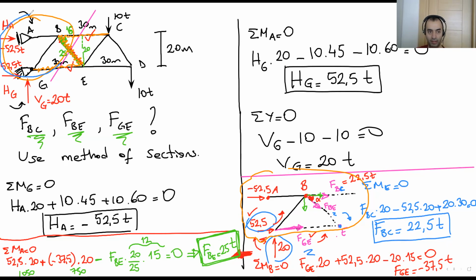I'm using this part. But here, the geometry I'm using as a moment point, this point. It's possible. I know the distance between these points. I can write the total moment zero equation for any point. I know that for each joint location, the moment is zero because there is a hinge at this point. Okay. In the first stage, I did that. I write the total ME is zero.